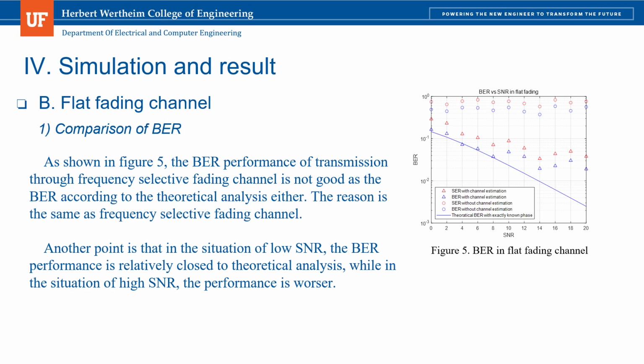And the second part is about the flat fading channel. We first need to do the comparison of BER. As shown in figure 5, the BER performance of transmission through the flat fading channel is not as good as the BER according to theoretical analysis either. The reason is the same as for the frequency selective fading channel.